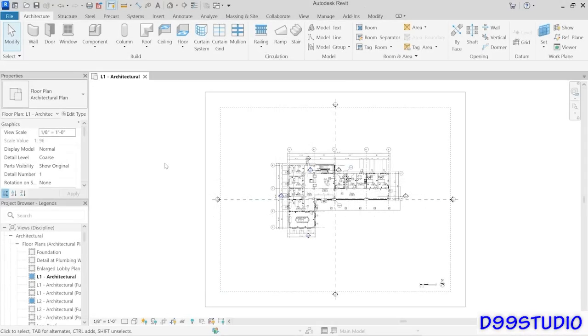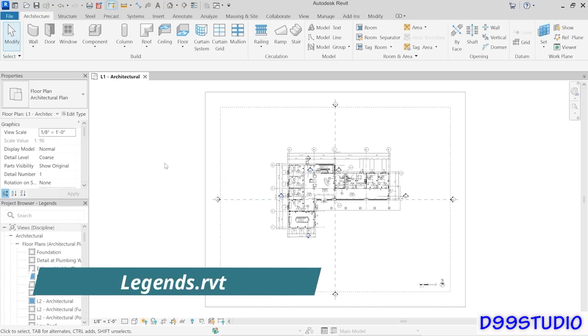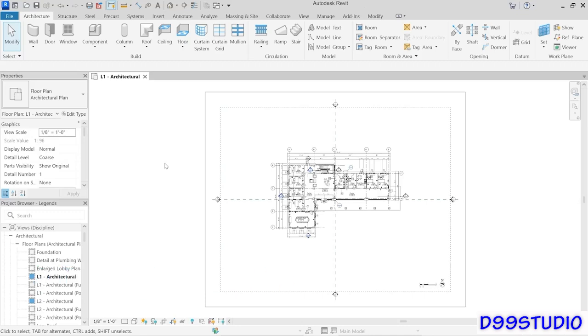Architectural documentation often has legends that define certain standard symbols that you're using throughout your document set. And you might see those for symbology. You might see them for different types of doors and windows. So in this video, we're going to create a door types legend, and we're going to do so using a special kind of view that Revit has called a legend view, appropriately enough.